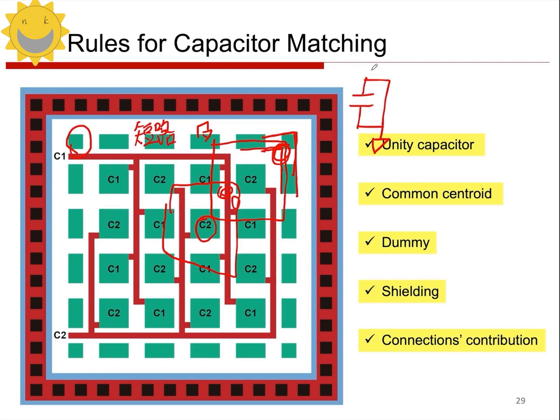So if you don't put one like this on the schematic, but I added a lot of dummy devices on the layout, then the dummy is indeed short-circuited up and down, and then grounded. So when you do LVS, if you don't do any optional operations, then it will report an error, because it does detect a lot of short-circuited devices on the layout, right? But there are none on the schematic, so it will report an error. Then there is usually an option in the LVS, that is, in the specific settings, to ignore such short-circuited devices.